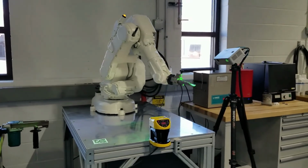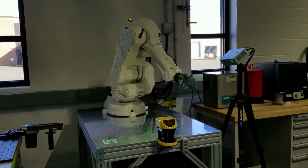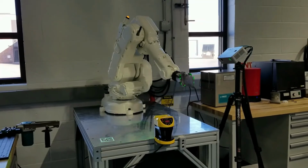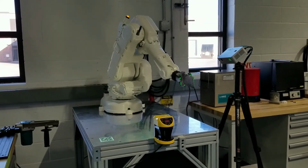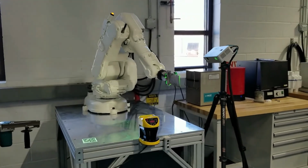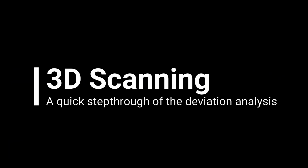So at this point, the robot is just turning the blade around so that we can get the scan from the other side. As I mentioned, the 3D scanning technology is line of sight, so you do need to present the surfaces, and they do need to be highlighted, or the light has to reflect off the surface to get that. So here's the sidebar that I mentioned before, prior to Kristi looking at the actual results.